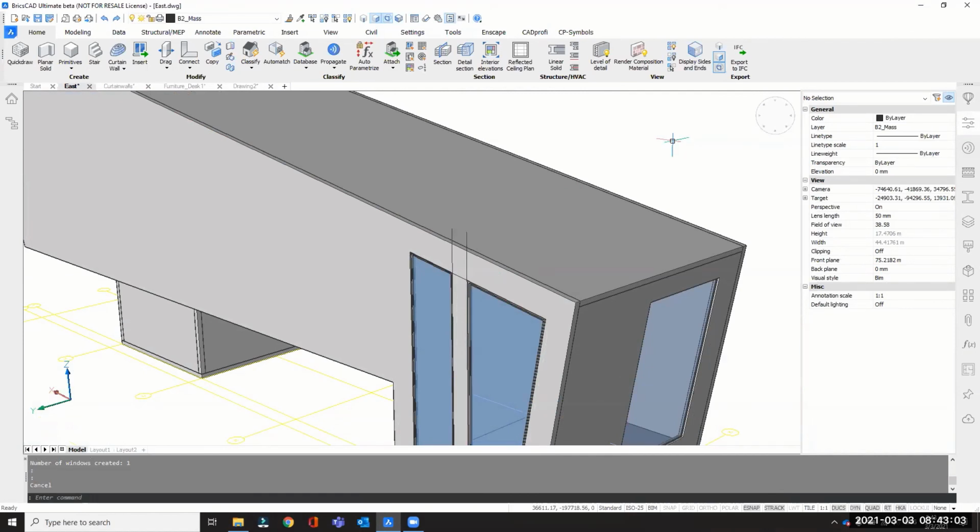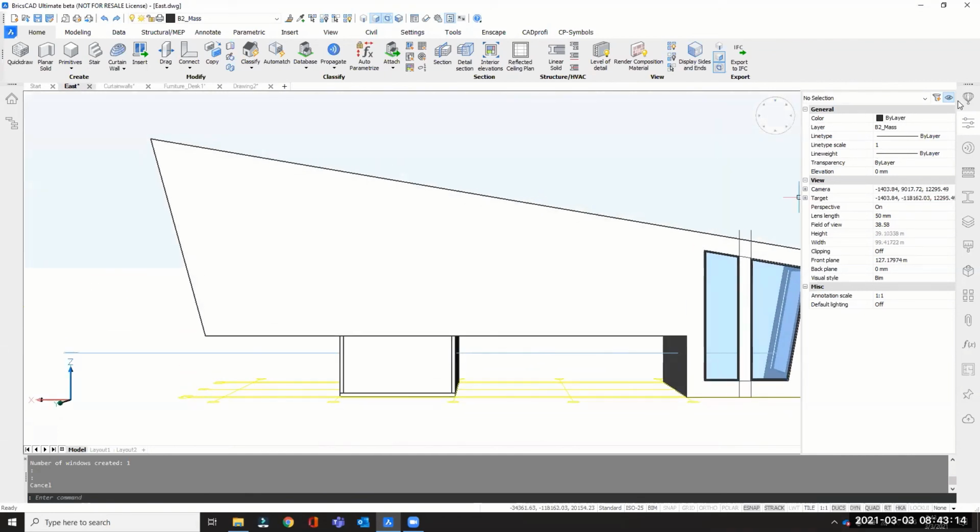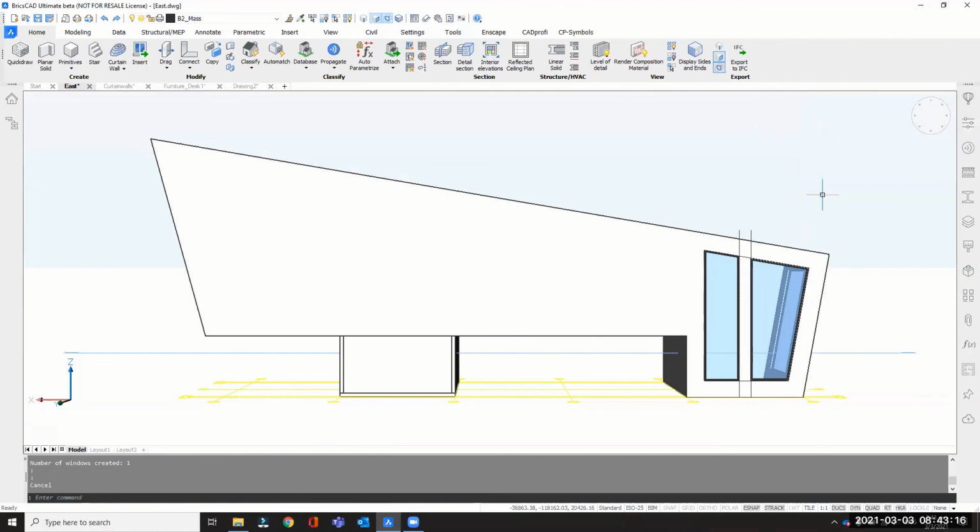And lastly, creating one with a grid. So let's just create one with a grid. And to do this, let's go to our back view of this model. Okay, so first, how do we create the grid so that we can create the window off of the grid? Under home, you would see here rectangular grid. Just here, it's being highlighted on my screen. Just click on that. Or if not, you can, of course, call the quad and select it from there.